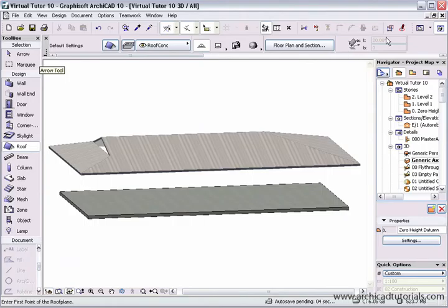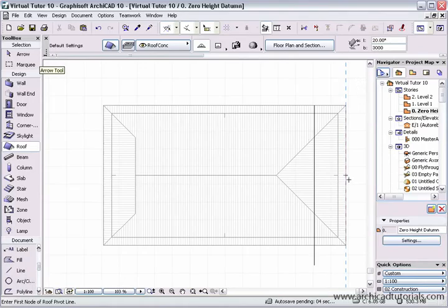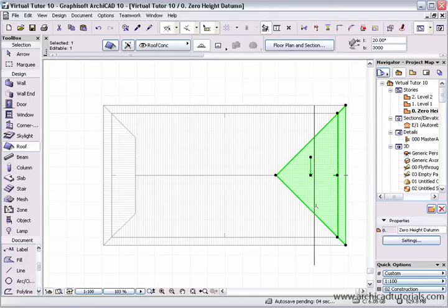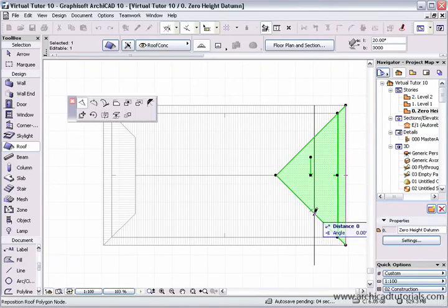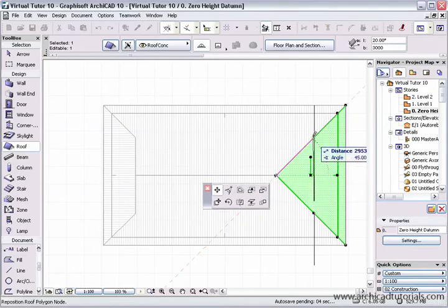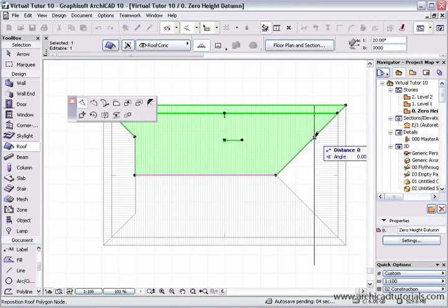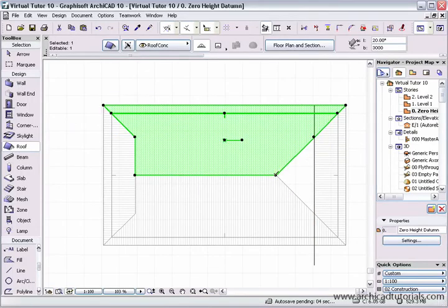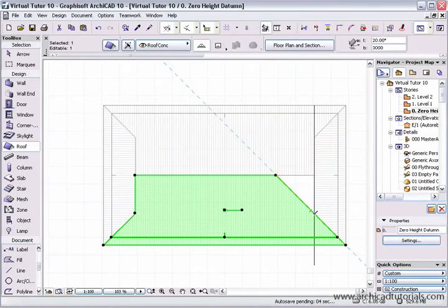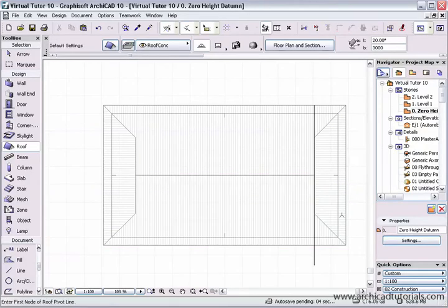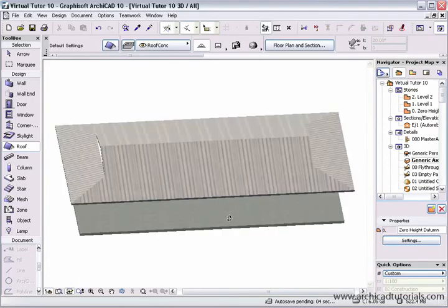So if I close that now, I'm going to do the same to the other side quickly. Hold the Shift key down, left mouse click on it, add a node at that intersection, and grab this node, drag it up to there, select this roof plane, left mouse click at that intersection, drag this mouse along, left mouse select that roof section, add a node there, and drag that across to there. Then I'm just going to select the line and delete that. So there's a Dutch hip.